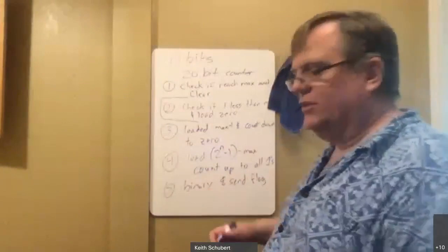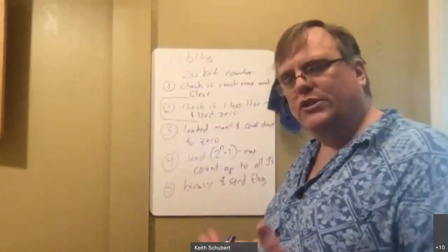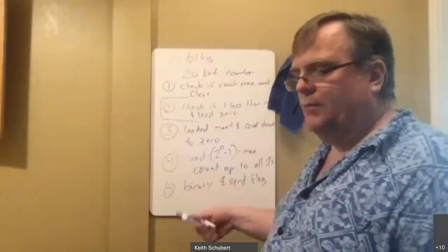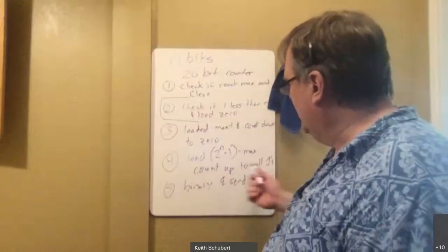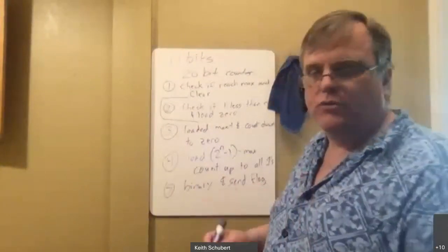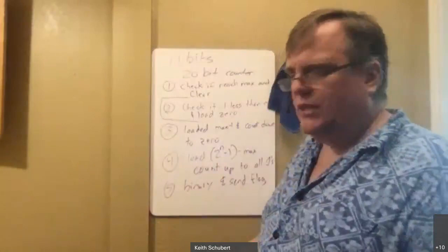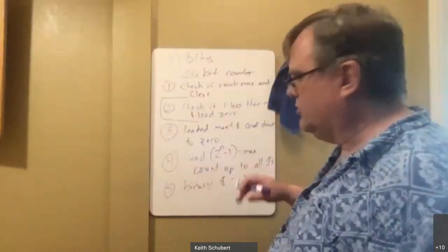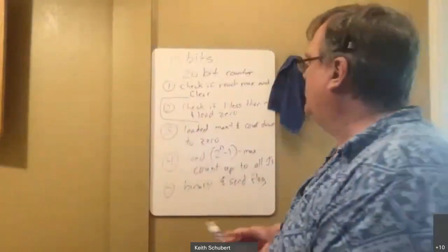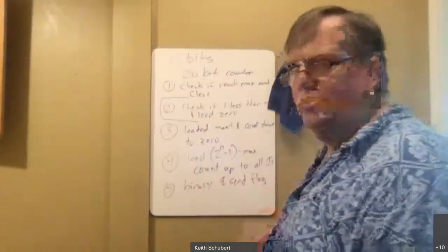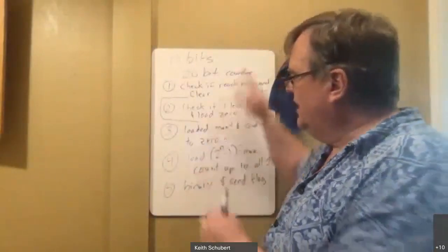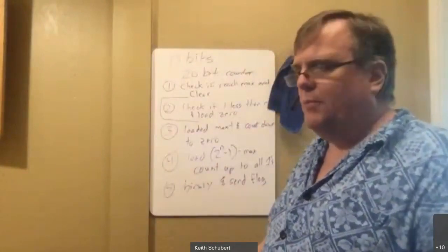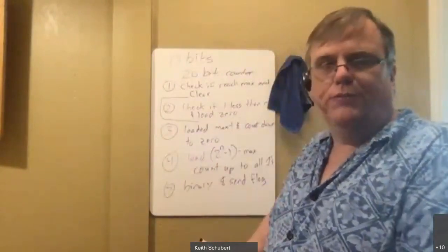That just makes an easy thing to build, because oftentimes we'll want to just keep reproducing a safe design. And that safe design might have a binary load to it. So when that flag comes out, I can just have it automatically have all zeros set up on the input. And when the flag comes in, I use that flag to go to the load command. Right? But I can also send that flag to other things as the clock pulse. It's another way I can do it. Right. Like I said, there are so many of these ways. When you start thinking about them, you'll start coming up with just dozens of minor little variants to them.